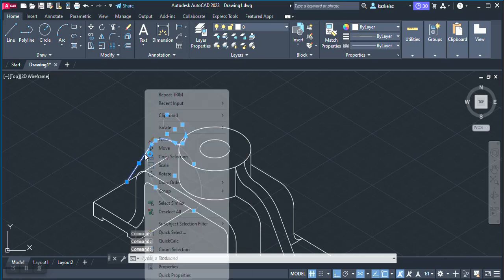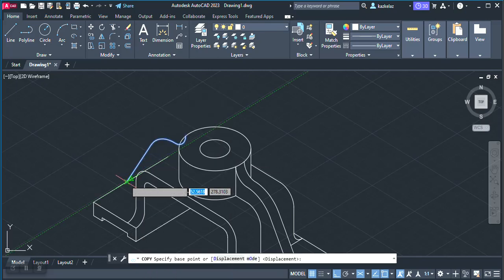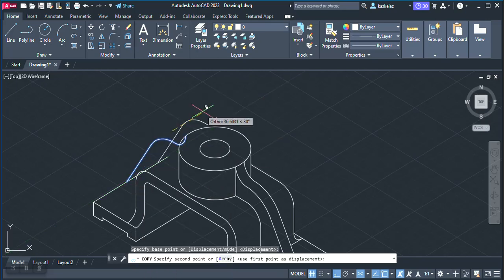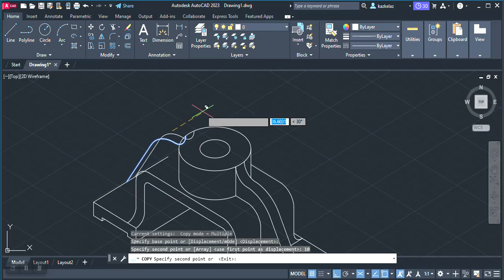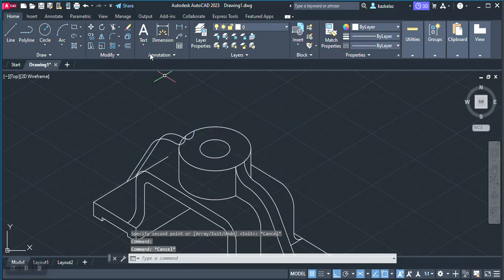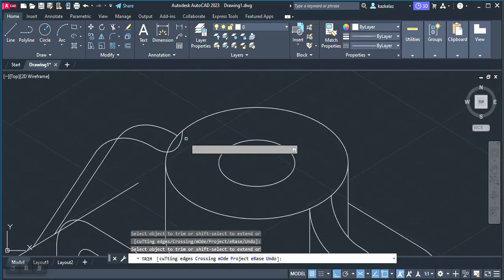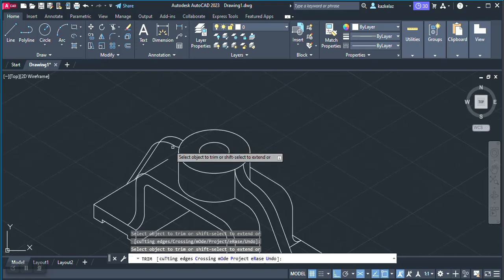For this one we have 4 holes, diameter 13, so the radius is 6.5. If you check the drawing, it's 19 from there and 19 from there, so 19 from the corner. So our distance of 19, then our 19 going inwards is that line. I'm going to select elliptical arc as a circle, go to that point, and then type 6.5, enter, and I draw the circle, complete revolution.